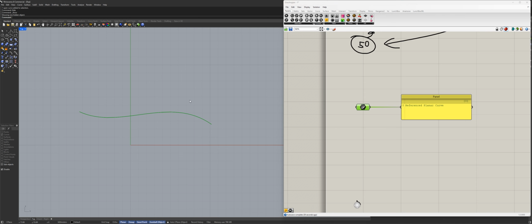And of course, as I said, it's a live link. So if I pick my curve and I move it somewhere else, as you can see, its streamed version will follow, right? It samples it and then pushes it back, because I can do something with this curve, modify that, and then it will be visualized here in the Rhino. And this is true not only for the curves, it's true for absolutely any type of data you stream from Rhino to the Grasshopper. So this is a universal approach, okay?